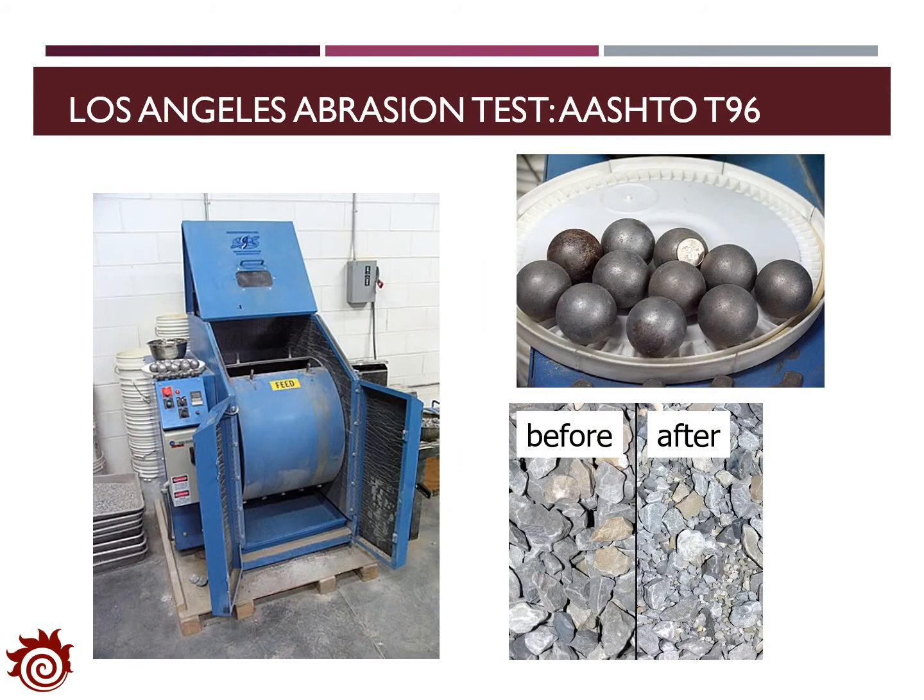The table also lists that Los Angeles abrasion loss is one important factor for the selection of the base course materials. Usually this loss is determined by the Los Angeles abrasion test, which is defined in AASHTO T 96. The figures in this page show the instruments applied for the test. Basically, the Los Angeles abrasion test is applied to produce the abrasive action.